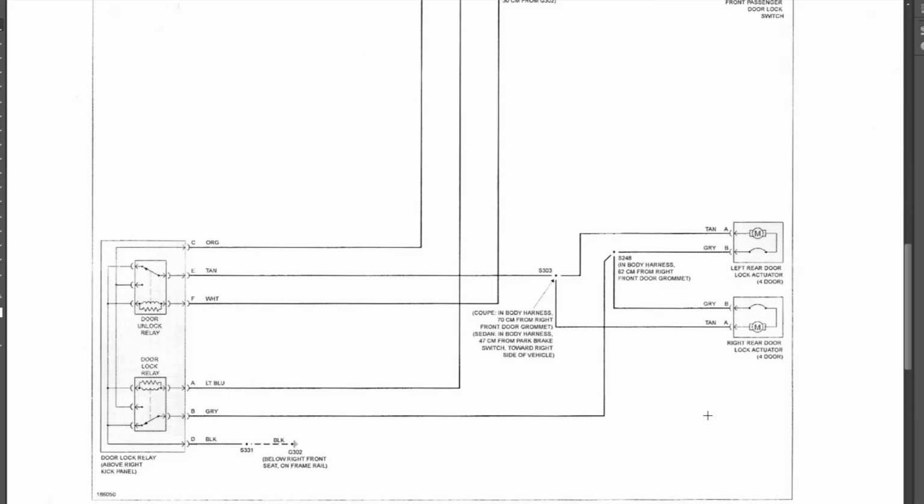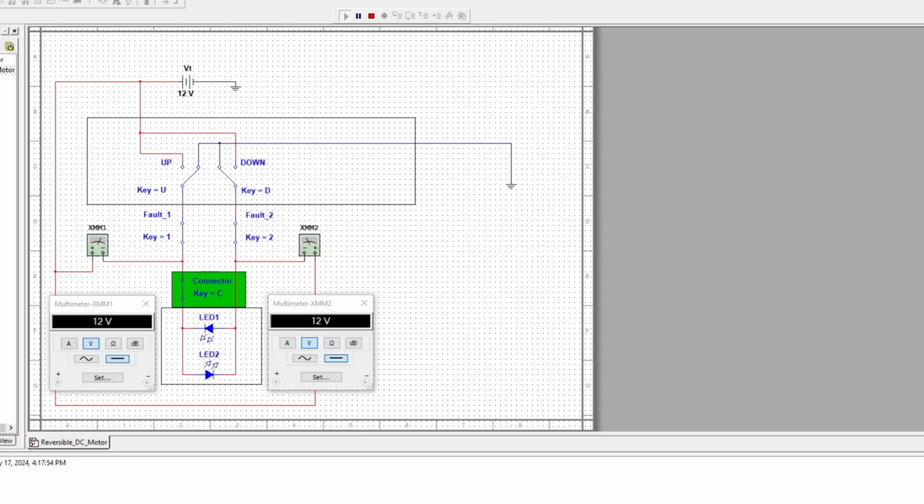can test a whole lot of the circuitry very, very quick. The only thing you have to remember in these cases is you actually need to isolate the part of the circuit that you intended to test so it doesn't backfeed and it starts giving you false readings where it doesn't look like there's a fault. But there is, but you can't tell on the voltmeter. And the reason why is you haven't isolated that circuit. Isolate that circuit and the problem instantly basically jumps in your face, raises the flag and says, here I am.